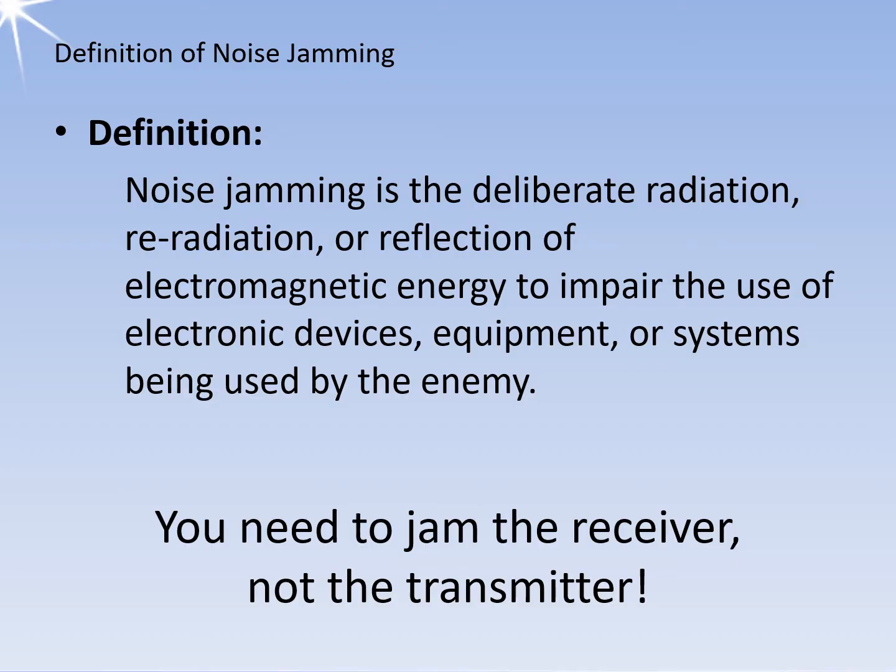The only thing a jamming transmitter can do is interfere with the sensitive receivers by either driving them into saturation or constantly transmitting interfering phase jumps to prevent the decoding of the signals. The exception is when the transponders of aircraft are to be jammed. They can then no longer respond to the interrogations of the secondary radar and the enemy radar can no longer distinguish between friend or foe.